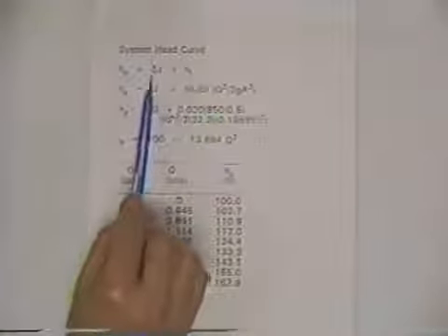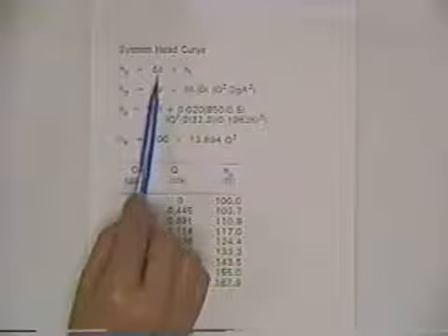Okay, let's do the part that we've done in previous examples, and that's relate the system head curve, we call it, relating the characteristics of the system independently of the pump. And so we use the energy equation just now and determine from the energy equation that the head added by the pump, that term in the energy equation, is going to have to take care of the delta Z, and it's going to have to take care of the head loss.